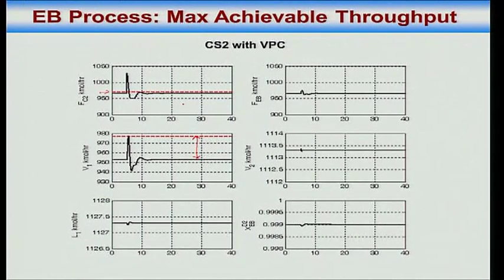This is only for one disturbance in the flow sensor ethylene. There are n number of disturbances operating at any given point in time. Not only the flow sensor, here the DEB recycle flow sensor, the total benzene flow sensor, the temperature sensor on the column, the heat loss in the column, day, night, etc. All these things are operating at the same time. Each one of these disturbances will add an extra back off. So what seems like okay, only 0.5% loss, may actually turn out to be 1 or 2% when you take the effect of everything together.